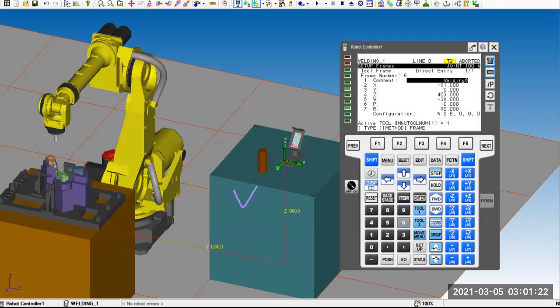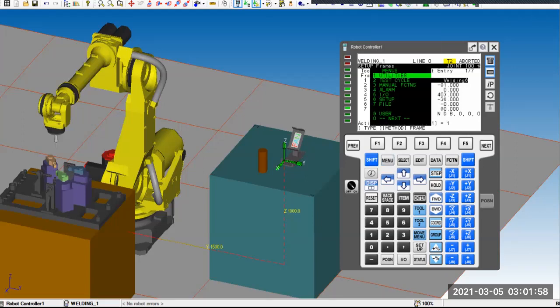Remember the tool frame, right? This is basically where we left off before. It's still in the tool frame menu, with the method and tool frame number 6. Here are some details regarding the menu operation with the teach pendant. You want to set up different frames, but because you are already in the tool frame setup window, whenever you press menu and 6 setup, you directly go in there because that's where you left off.